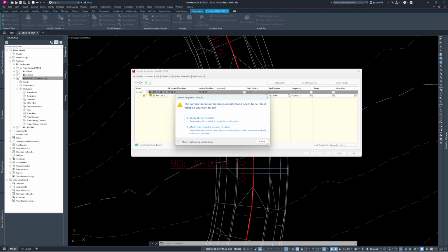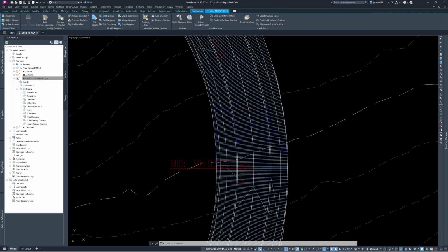Okay, I'm going to set those back. Now your surface might be a little bit smoother because every single time one of those blue lines crosses the contour, it's sampling it. So you have a lot more sample points. It's not interpolating nearly as much on these curves.